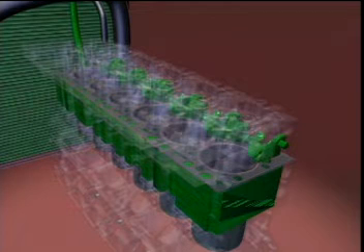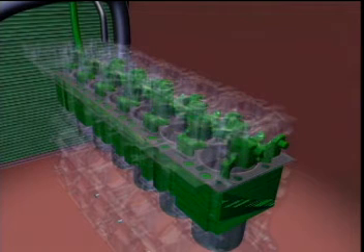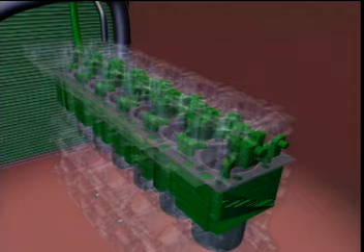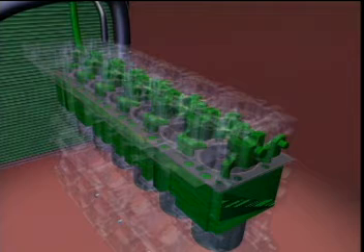Coolant flowing through the 2 passages per cylinder in the left side of the cylinder head gasket flows to the upper water cavity in the cylinder head, crosses over the valve seats and bridges. The coolant in the lower water jacket in the cylinder head connects to the upper water jacket through a series of passages in the cylinder head.